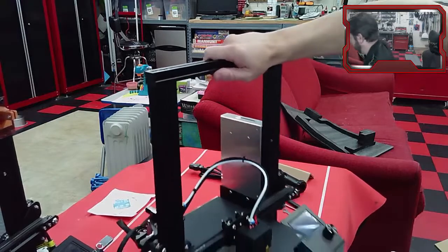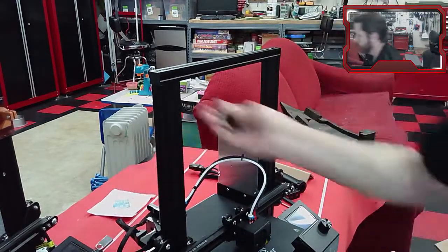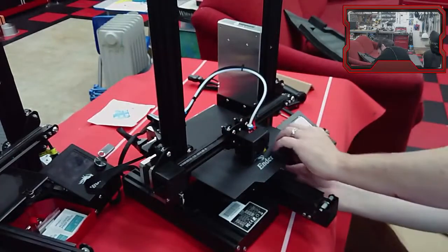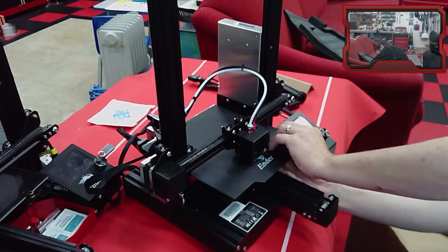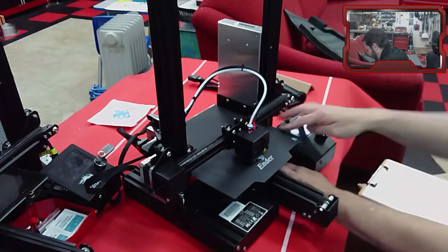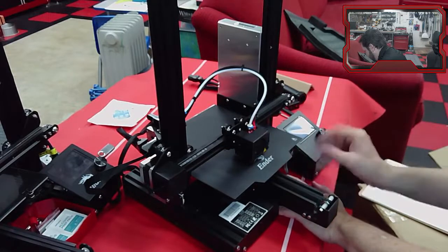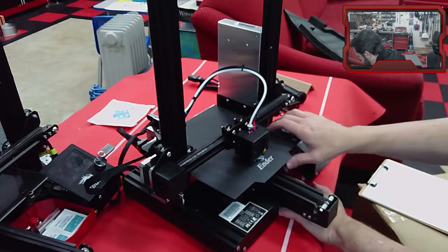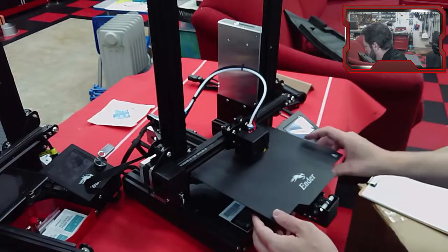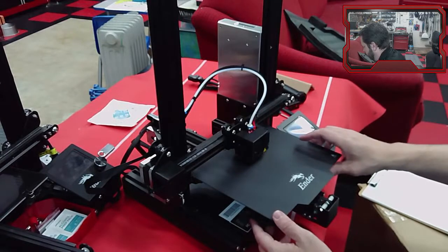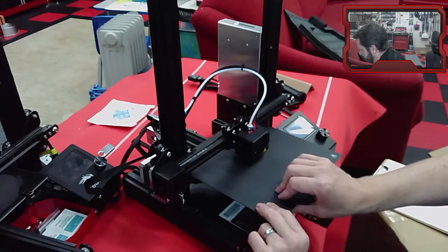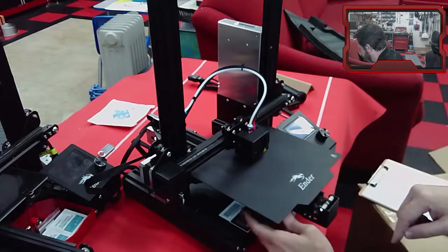All right, so I did notice that this wheel was not attached, which goes down here. This is the bed leveling. It's rubbing up against that wire ribbon cable. That's how you level the bed on this by default: there are 4 springs, one at each corner, and you tighten them down to create different heights for the bed. So if this is too high, you tighten this down and it'll bring that corner down.